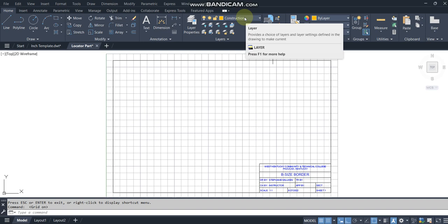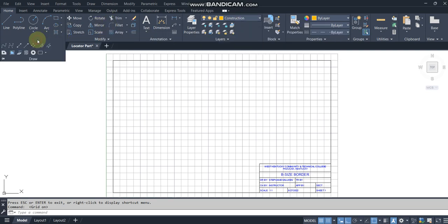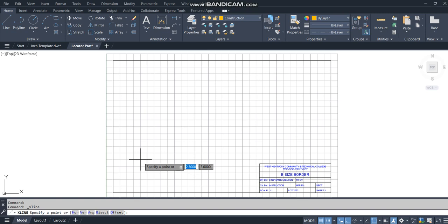So when you look at the multi-view projection unit, it talks about identifying the overall width, height, and depth to make up your three views. So that's what we're going to do first. I'm going to draw using a construction line, which makes a line of infinite length on my screen. Come out here to my open drawing space. I'm going to pick a point and run the line in a horizontal direction. From that same point, I'm going to run a line in a vertical direction. That's going to give me the lower corner of my front view.